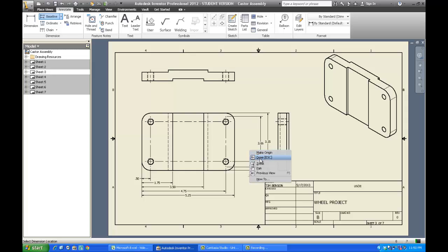So we're going to have to cheat it and try it the old-fashioned way. Okay. We'll do it the old-fashioned way for right now. Baseline it. And I'm going to go from here to right there. Right there to right there. And then I'm going to tell it to continue. There. Now it's got my dimensions right. Click where I want to place them. Create them. Now the reason I put dimensions between the views is so I can see the relationships here.